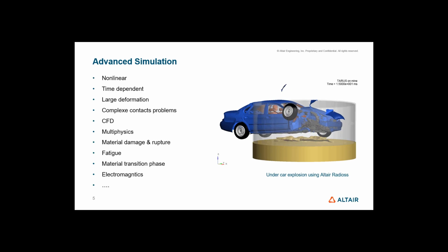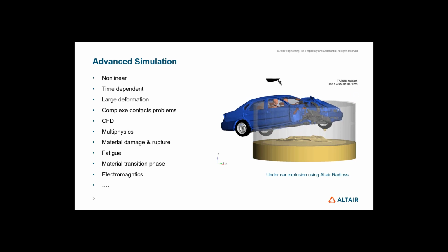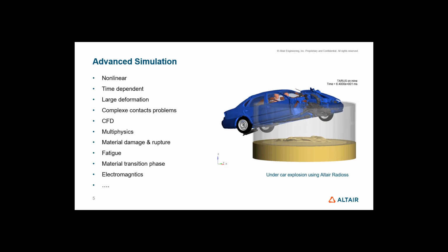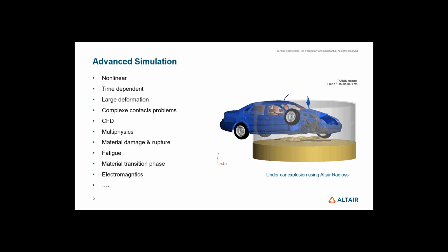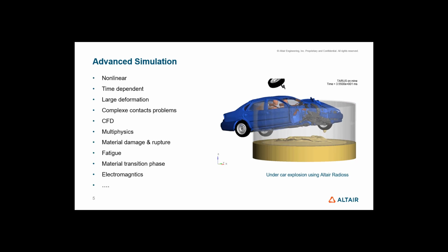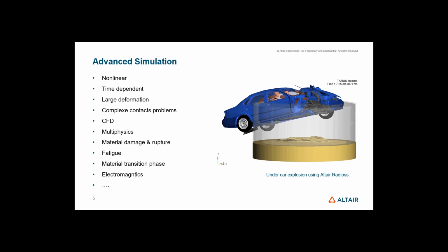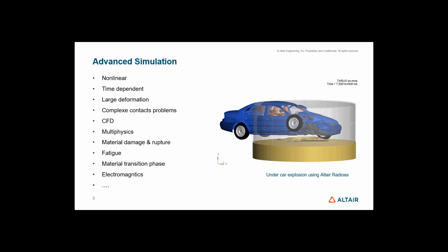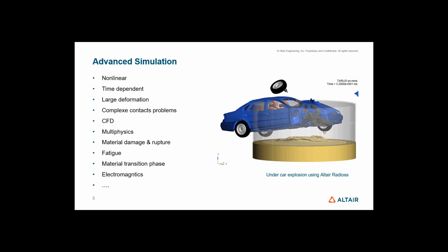For example, here, when we simulate the explosion of a mine under a car, we have many topics to consider, such as high nonlinearities, time-dependent problem, large deformation of parts, complex contact problems, ruptures, and also the fact that we have to simulate structure and air for this simulation, so multiphysics problems.